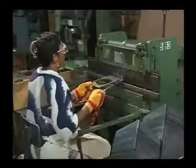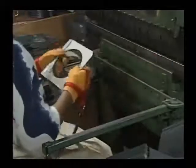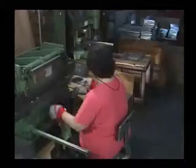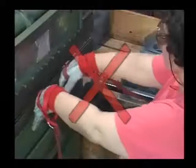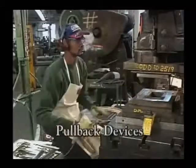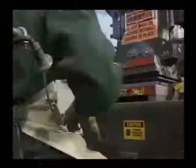Unlike other guards and devices, restraint and pullback devices are attached to the workers they protect. Restraining devices use short straps or cables that are attached to an operator's wrists. These protect workers by preventing their hands from entering into the point of operation of the machine that they are using. To be effective, the cable must be long enough for a worker to manipulate materials being used, but short enough to prevent their hands and fingers from entering the danger zones. Pullback devices permit machine operators unrestricted access to a point of operation between machine movements, but will retract their hands if they are too close to the point of operation when the machine starts moving.